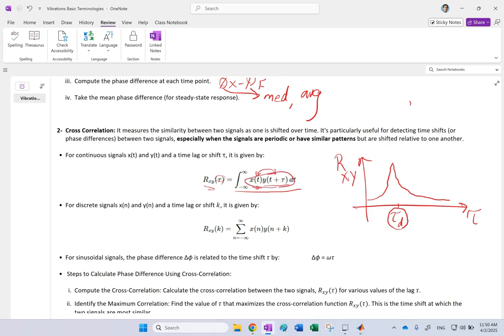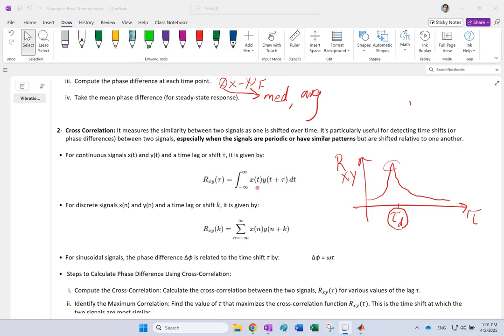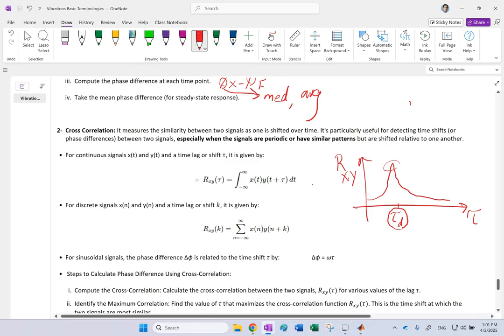So this is kind of like something signal squared. So you get the maximum overlap between the two signals, ideally perfectly 100% overlap if you calculate this correctly. And in discrete signals, this integral is going to be replaced by sigma. By the way, you see that the limits here for the time, or the n, the sample number, go from negative infinity to infinity. This is assuming that the two signals are infinite signals.